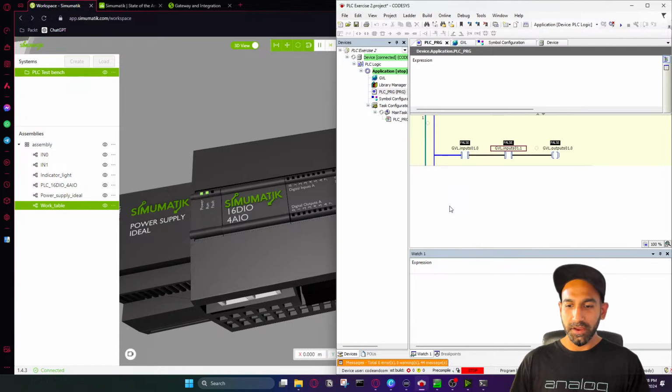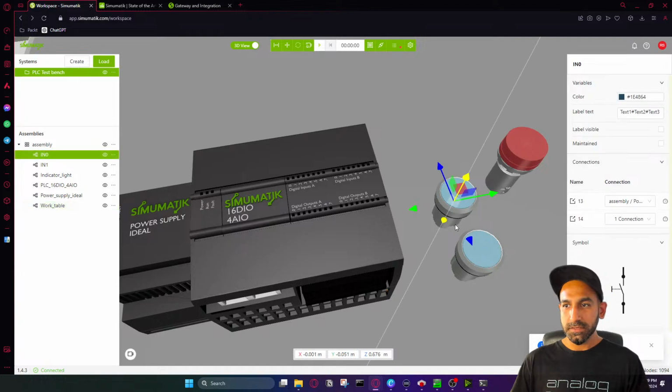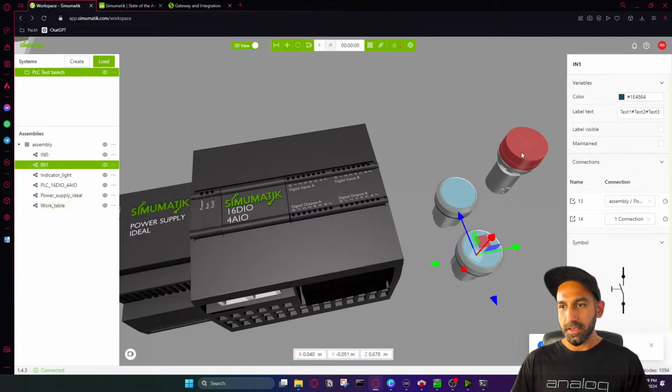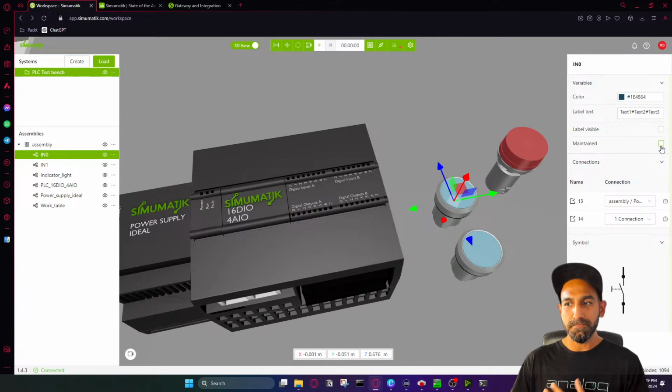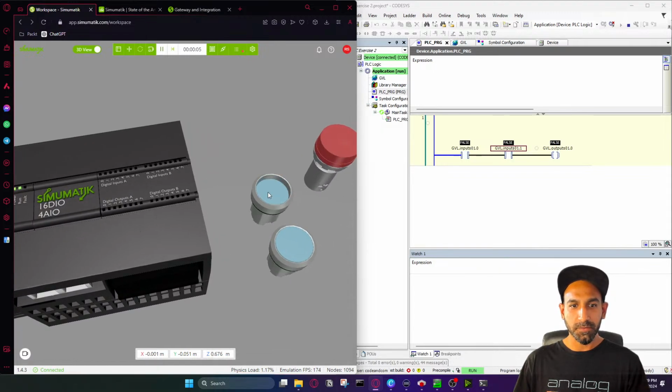Now there's one limitation here because I can't press them together. There's only one button you can interact with. In this case, you can see we have an option to maybe use it as maintained. Although it's not part of the exercise, to show you the logic, I can use it as maintained. So now, let's hide that, and when I press this, it is now maintained. So this input is true. Second input, I can turn it on here and my lamp is on.